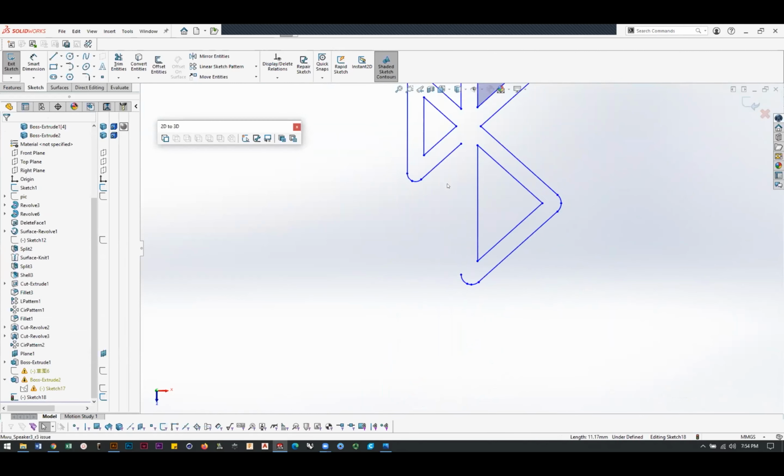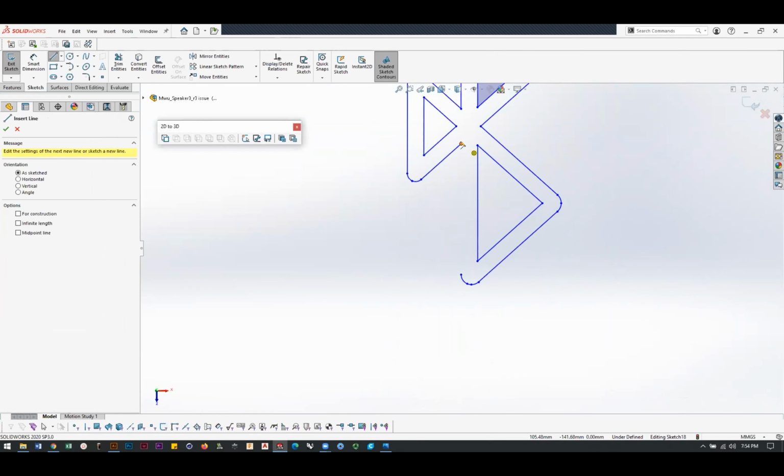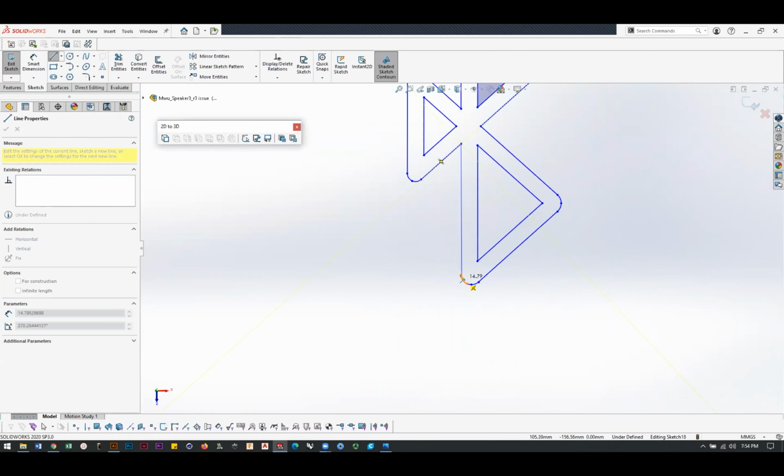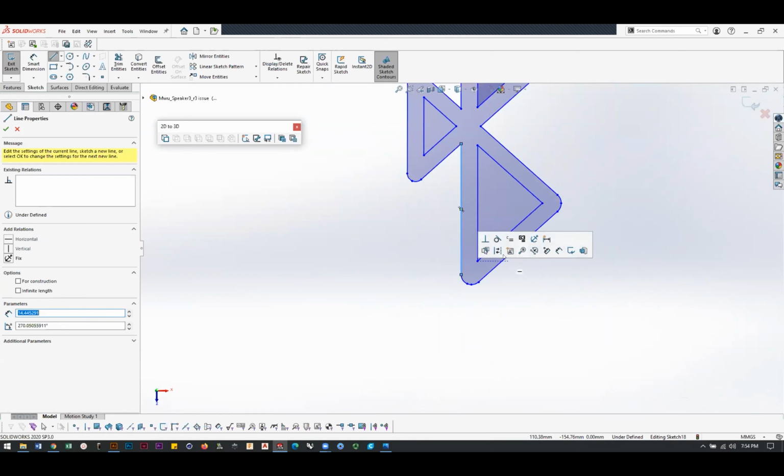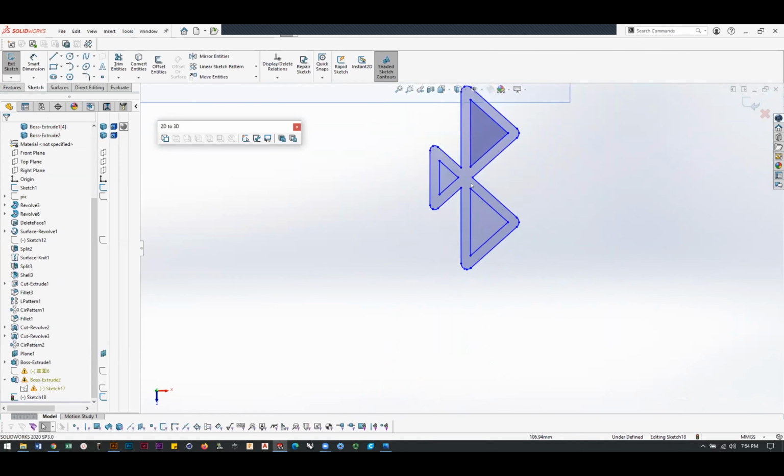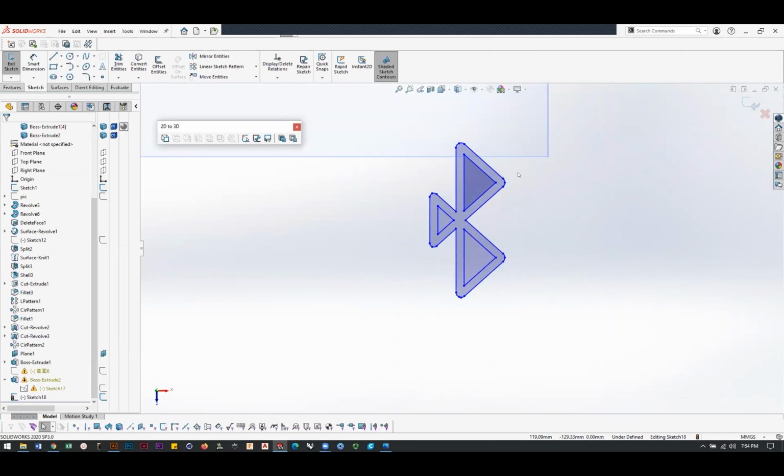Hey guys, anybody else in the class have any issues like this where you're seeing differences in the line work that you're getting in SolidWorks versus what you drew in Illustrator? For me in Illustrator, I just drew the whole thing as one line instead of flipping and joining two different drawings, which helped.